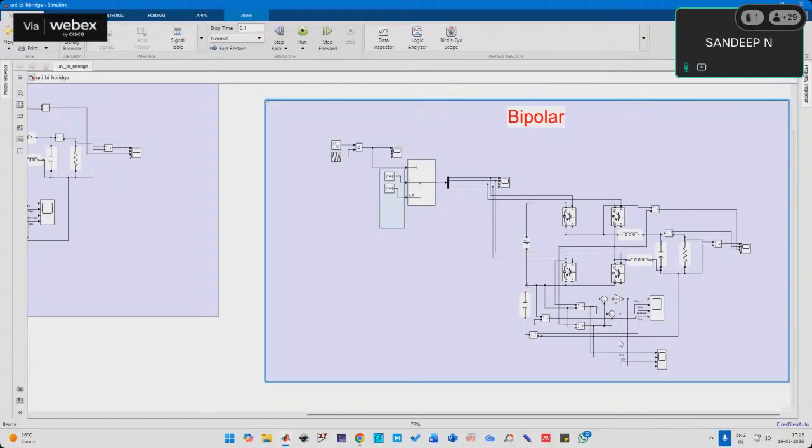Okay, so this is the capacitance, and typically the capacitance value goes from 20 to 100 nanofarad per kilowatt. That is the typical range. And this again changes. This is not a fixed value. The capacitance value depends on the way the module, the panel is, like the dust, whether the module is in a dusty environment or moisture, all those things are going to affect the capacitance value. So anywhere in the range of 20 to 100 nanofarad per kilowatt is fine. Okay. So this is the capacitance.